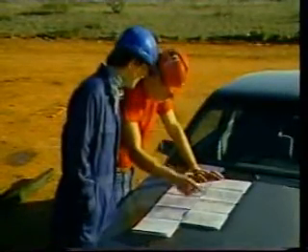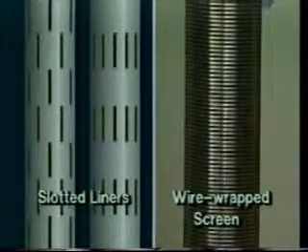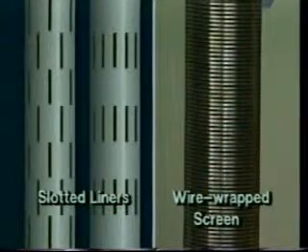If rate control and the natural arching tendencies of the formation sand are unsuccessful in controlling sand production, then other methods must be considered. Mechanical methods are the most common and include plain screens, pre-packed screens and filters, and gravel packs. The plain screens include slotted liners and wire-wrapped screens.